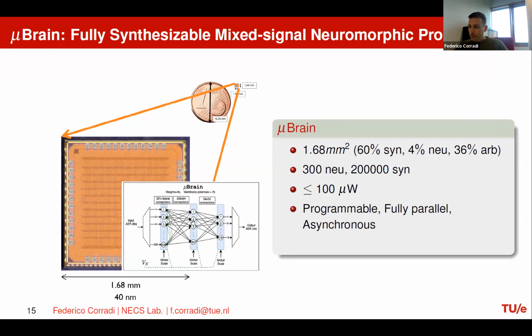I was wondering, with this kind of memory organization, are you able to deal with convolutions where the same weights are used on multiple input feature maps and for multiple output feature maps? Good question. With this type of architecture it will be inefficient, because weight sharing is not implemented.